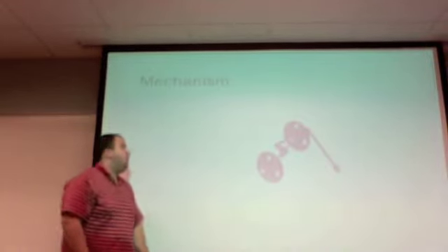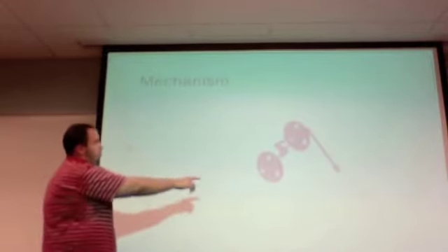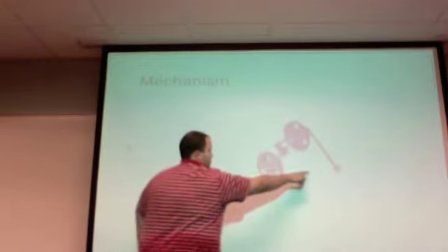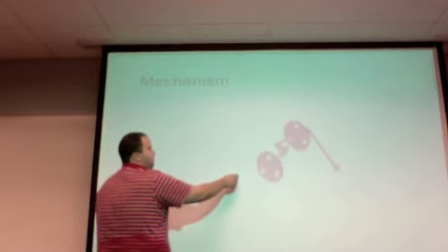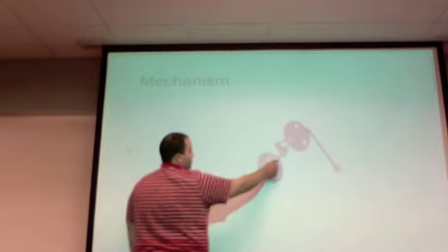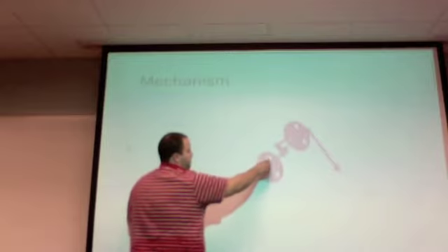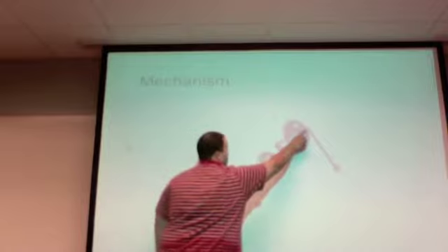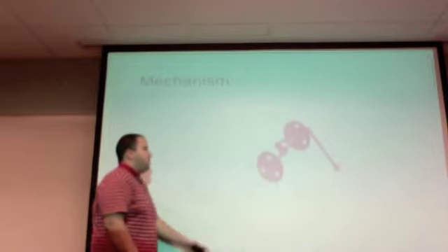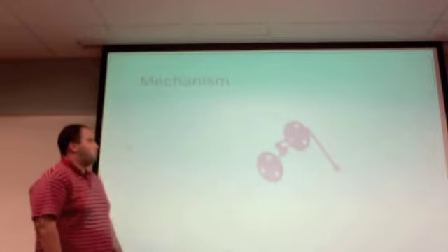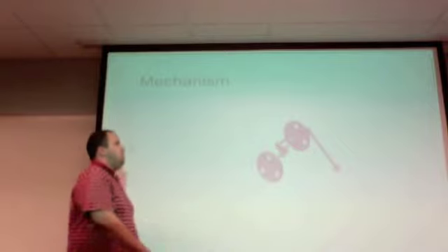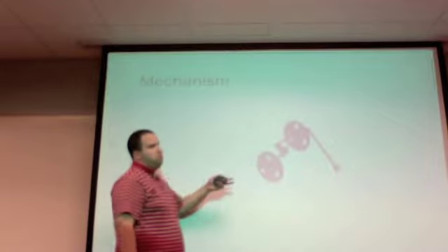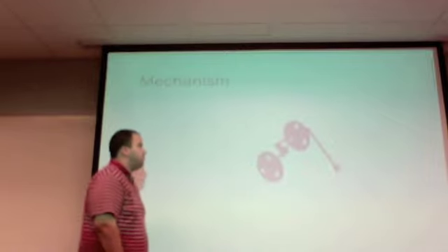Thank you. In this mechanism, this is a 4-bar crank mechanism. As you can see, the first bar is the ground, where these 2 points are lined up. The second bar is the shorter one, which in this special case is the crank for these 2 wheels. And you have the other 2 bars, this one being the longer one. In this scenario, a user could manipulate said lever to turn the crank and drive the mechanism through a railroad track. And this is how it works.